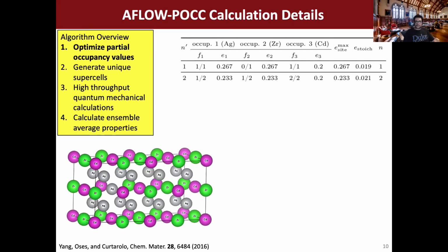And we're going to do the same thing for the cadmium. Again, the best strategy for having a supercell size of 2 is actually to have the cadmium in both. So the algorithm is doing this analysis for you. It's telling you that the best way to do it is to have a cadmium in both. Once we get to a supercell size of 5, we can actually have one of these cells not filled, it's going to have a vacancy. Once we get to 5, we can start to model a vacancy because the concentration is 0.2.